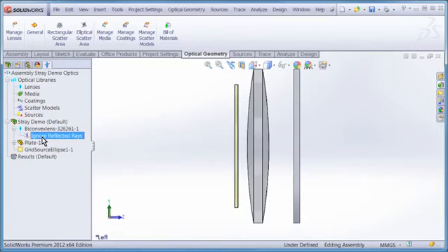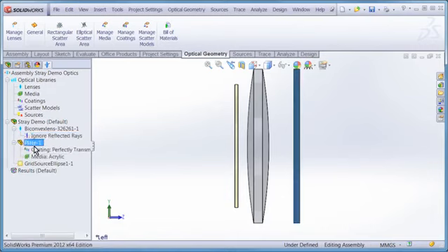What's going to happen in this instance is we will not see the Fresnel reflected rays from the optical surfaces, but the energy loss due to the Fresnel reflections will be taken into account in our calculations. And this surface here, the window, later on in the demonstration, we're going to turn into a diffusing component, but right now it's simply a perfectly transmissive plastic window.